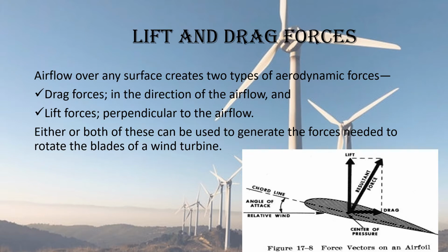Drag forces are in the direction of the airflow, whereas the lift forces are perpendicular to the airflow. Here in the figure, the resultant force or force vector is resolved trigonometrically into these components of lift and drag, and the angle of attack is the angle between the chord of an airfoil and the direction of the relative wind.